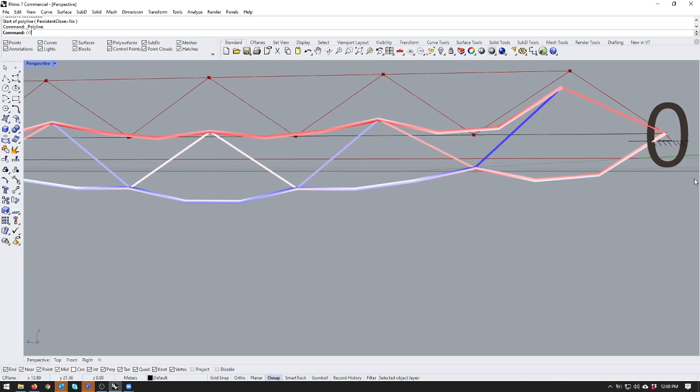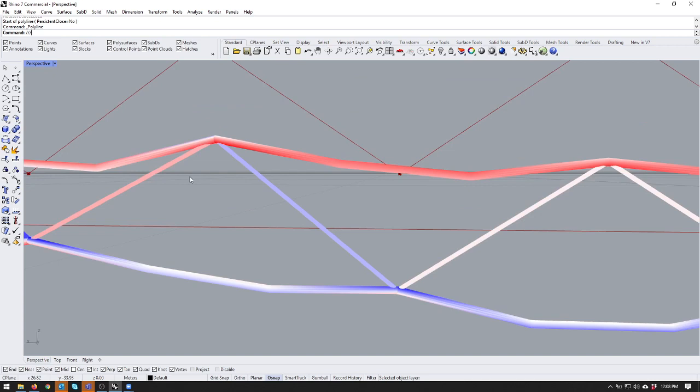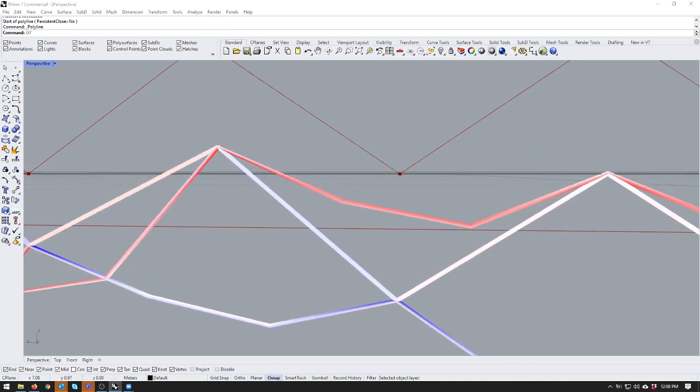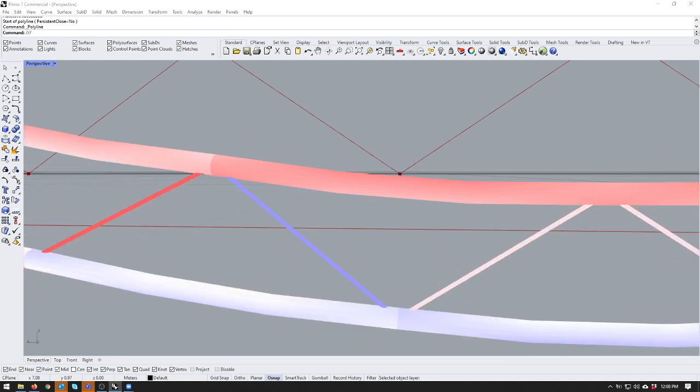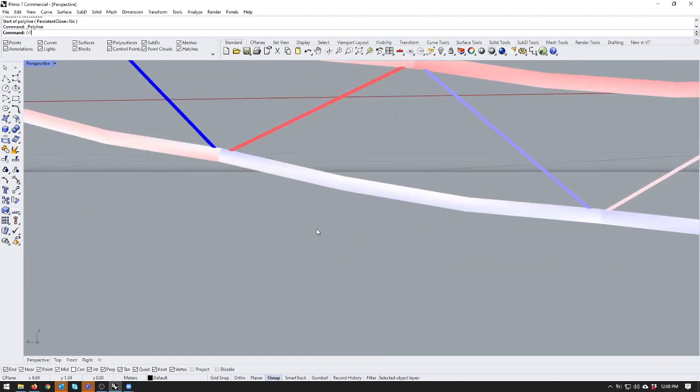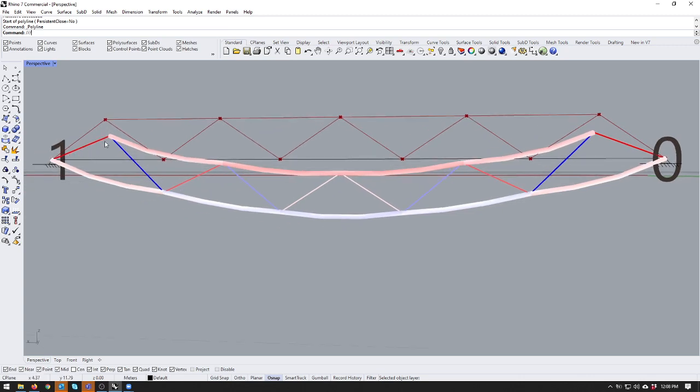So, just another thing that I've noticed previously is that people will design structures that have cables running through them. The cables don't have bending moments on them. I mean, they do. So they've modeled it so that it has a bending moment, which means you have this thin thing, and I'm going to pretend as if this circular hollow section is a cable now. Okay, so let's assume that these are cables, even though they're hollow. You can see this cable is in tension, right? And this cable's in compression.